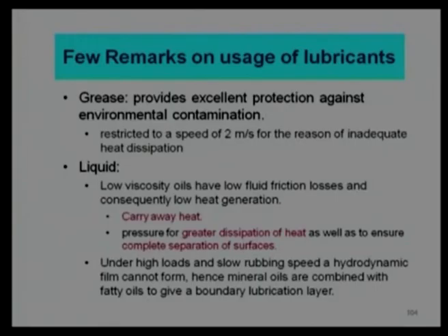Coming to the liquid side, we say prefer low viscosity oils. The major reason is there will be lesser shearing. If it is a Newtonian fluid, we can say shear stress is proportional to the viscosity. Lesser the viscosity, lesser will be the shear resistance. Lesser the shear resistance, lesser will be the friction force. Lesser the friction force, lesser will be the heat generation. So, low viscosity oils should be preferred compared to high viscosity oil, provided minimum film thickness is maintained.